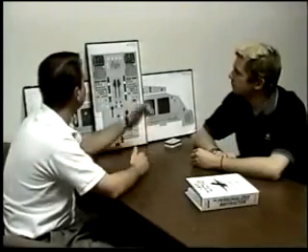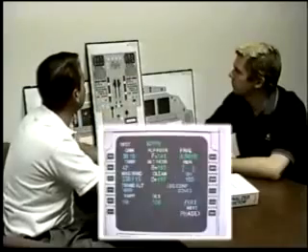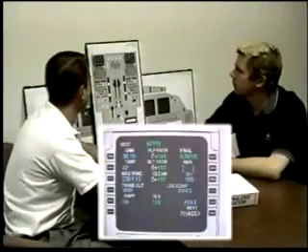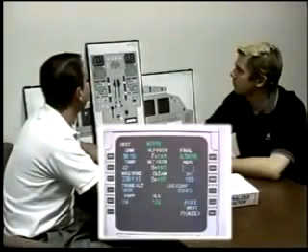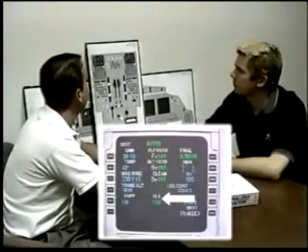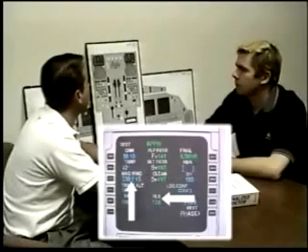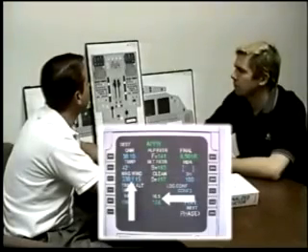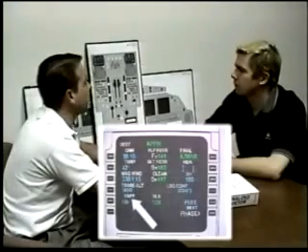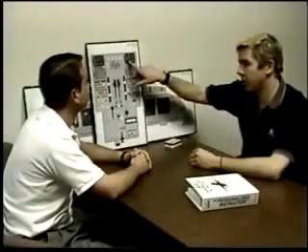On your MCDU, on the first officer side right here, we have the performance approach page. We have VLS that displays 128. The winds are currently 330 at 15, and you're landing on runway 33. Describe to me what our V approach would be in that scenario. Okay. On a 320, first of all, we start with VLS.